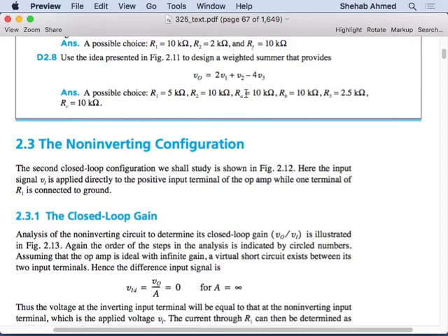So we discussed the inverting amplifier. Now we discuss something very similar, so the logic will be very similar to what we discussed for the inverting amplifier. We will discuss what is called a non-inverting amplifier. These are the two main families of op-amp amplifiers. Remember, the op-amp is an amplifier itself, but it has an open loop gain that is huge, so it was not very useful for constructing meaningful circuits. So we have two classes of amplifiers, inverting and non-inverting.